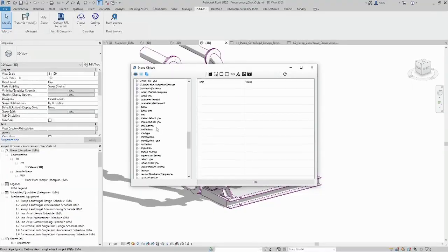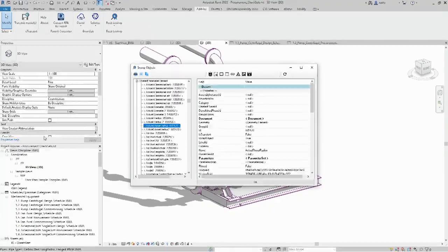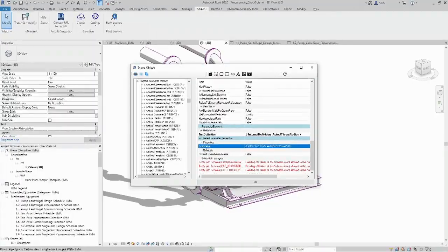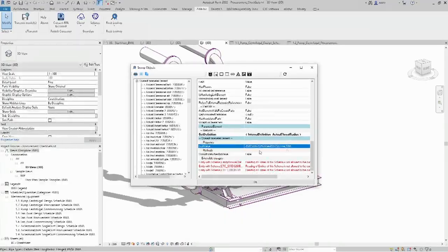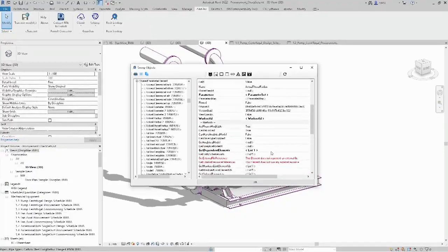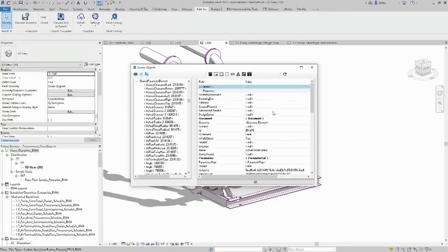So at the moment, we check for shared parameters. So I'm looking into the shared parameter elements, just select one of the parameters. And now here on the right, we have much more properties in the background in the Revit database than we can see in the Revit properties palette. And then we go a bit further down, so we see we have here the GUID value. So this is the string that I would put in, and this is the value that I'm looking for in the check set. But again, it would work with everything else that you see here in that list. Everything in the Revit database you can check with that setting API parameter.